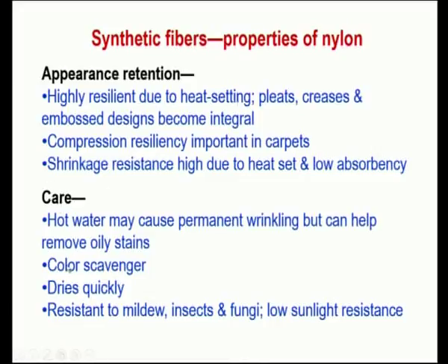How can we care for it? Hot water may cause permanent wrinkling, but can help remove oily stains, so we should not use hot water. It can be a color scavenger, so if you use any colored material there is a problem. It dries quickly and is resistant to mildew, insects and fungi. Low sunlight resistance is a very important property. It is resistant to fungus attack. Fungus can easily form in natural fiber, whereas in this kind of synthetic fabric it will not attack any kind of fungus or microorganism.